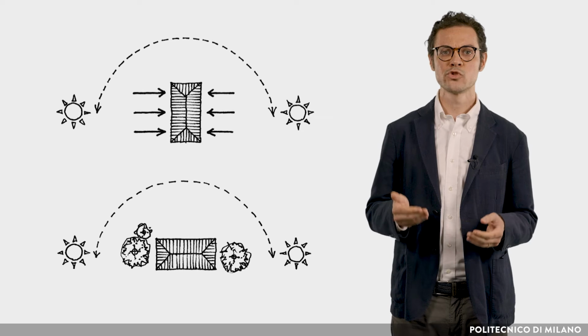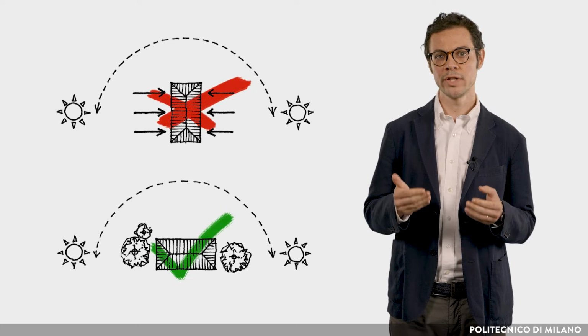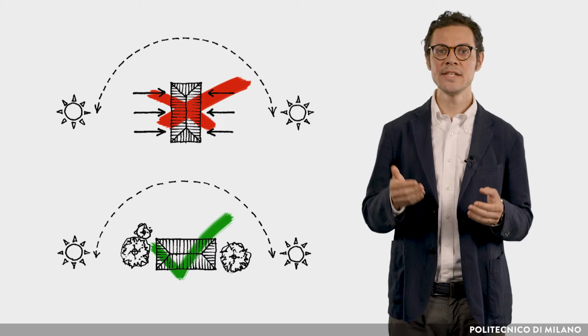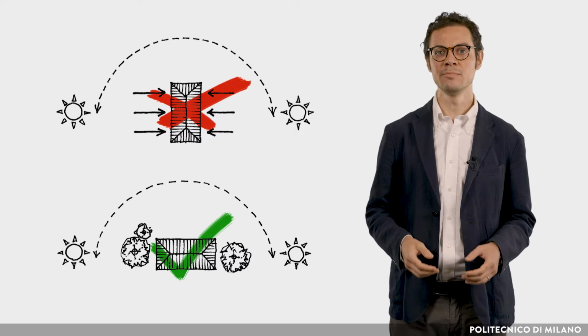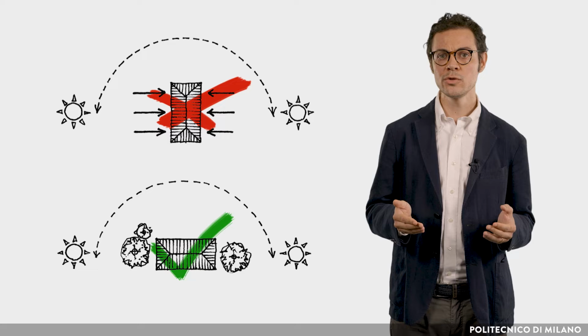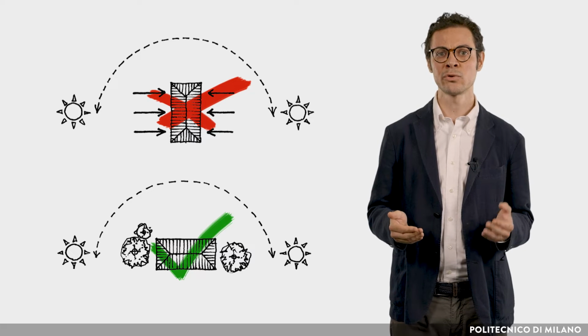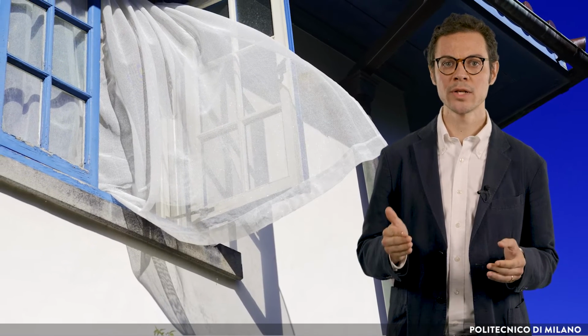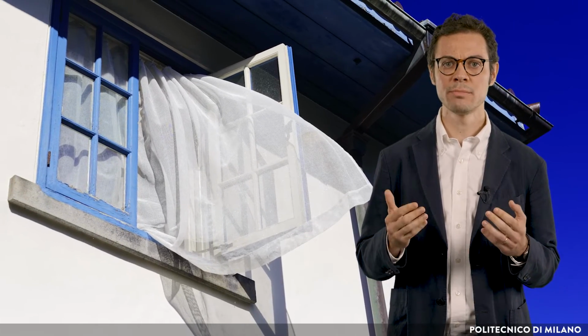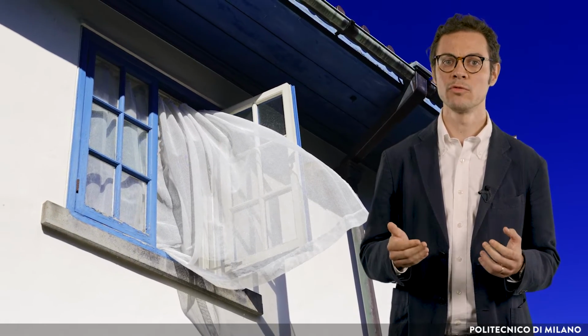Furthermore, buildings should preferably be oriented with a long axis running east-west to provide easy, effective shading and minimize east and west facing openings in order to reduce early morning and late afternoon heat gain. Also, natural ventilation should be properly addressed, since after sun shading it is the most important element affecting comfort.